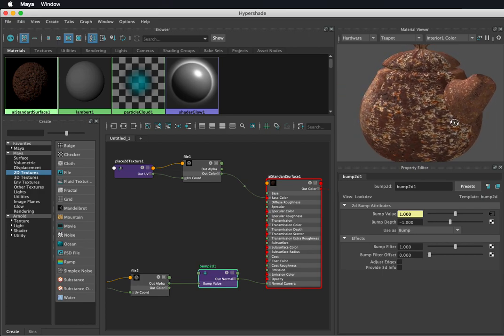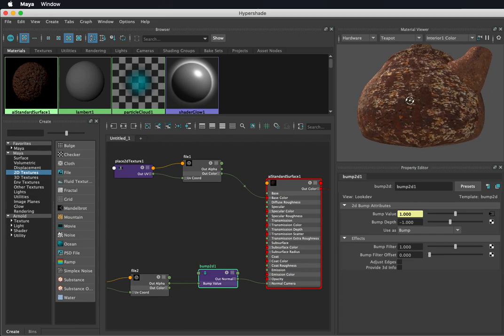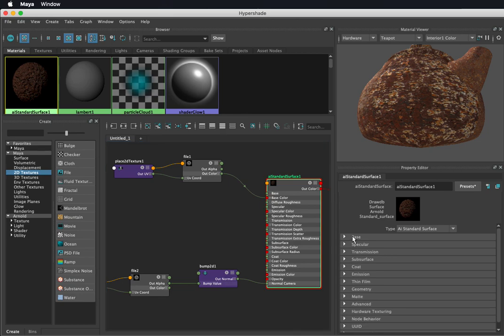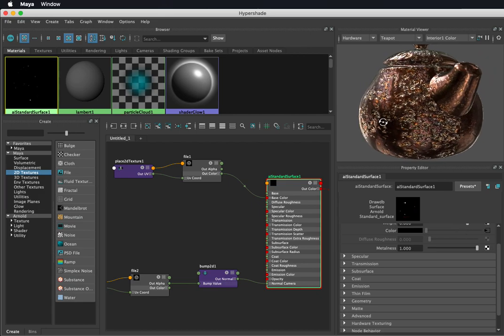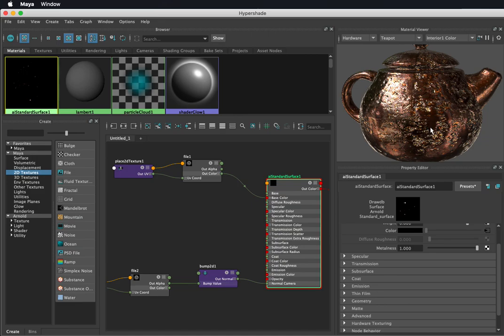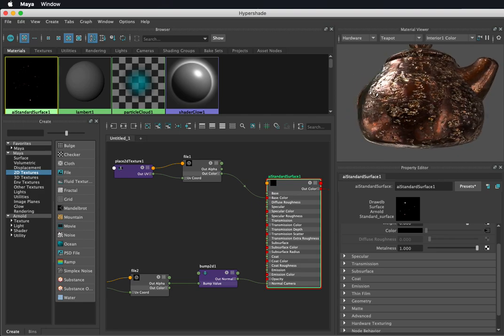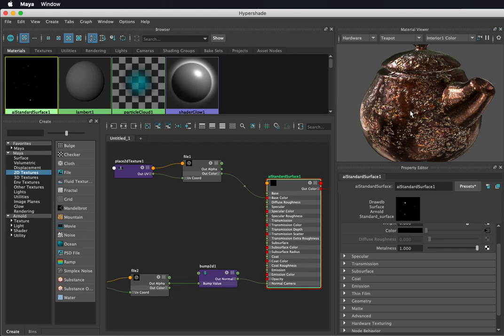But it'd be nice if we added in a bit of metalness as well. For the metalness, what we want to do is take these areas that are white and make metal shine through in those areas, but in areas that are really rusty, we want that rust texture to stay. So if I came back over here and dialed up the metalness value, under base here, I get this effect, which looks kind of cool, right? It's a nice really shiny copper texture, and the bumps in it are really pronounced, but it's not exactly what I want, because now it doesn't look rusty anymore. It looks like pitted copper.